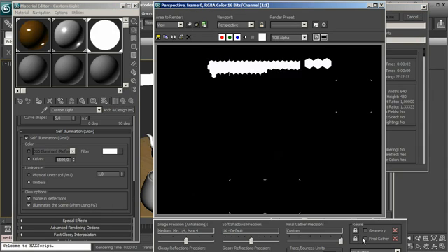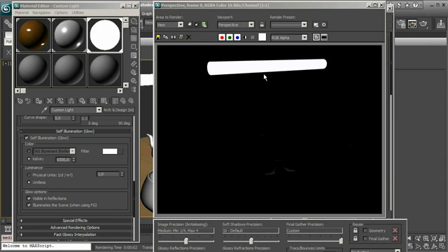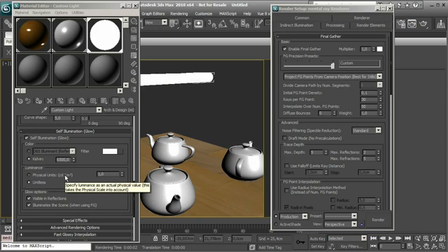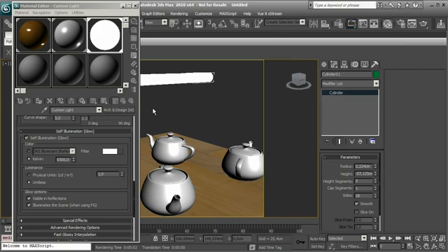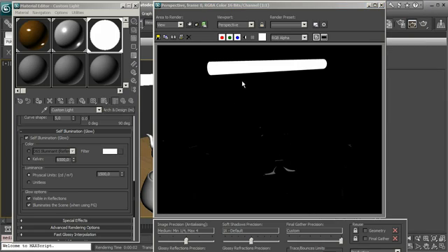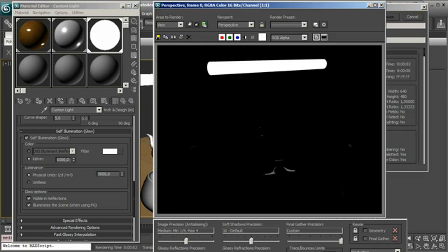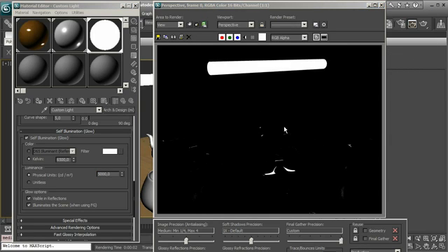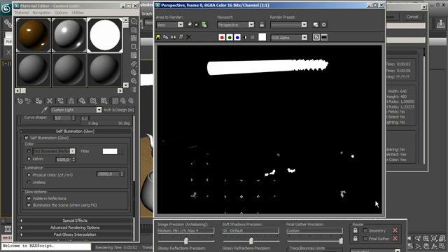So actually we can illuminate the scene using this tubular, but we have to set the power. So I created the scene using the right unit measure, so we can go to physical units, and we have cd per square meter, so we can see if it's okay or not. And you see that we need more power. Let's try with 5000. Let's try to illuminate. You see that we start to have some kind of illumination, and let's go to 50,000.